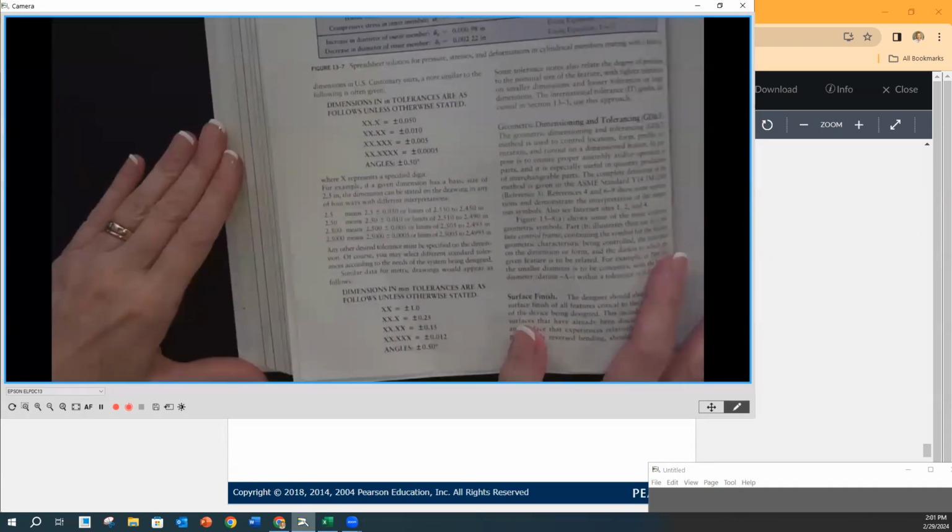You're going to notice that this section just talks about and reviews, when you have a drawing, you have some ability to have some standard tolerances. So again, that title block tolerance is going to dictate when you specify dimensions without a tolerance. It's going to default to what's in the title block.